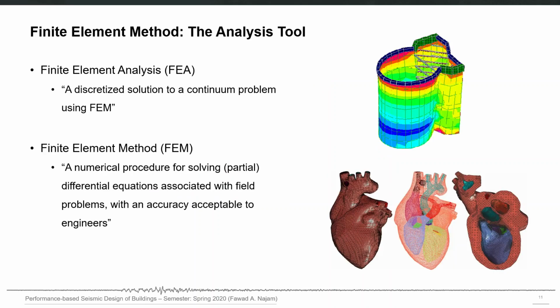The finite element method is a method based on discretization, and the underlying idea is that we can divide our structure into simple elements, and the behavior of those elements can be well understood and described by simple mathematical relationships. So finite element analysis is a discretized solution to a continuum problem using FEM, the finite element method, and that method is a numerical procedure for solving partial or ordinary differential equations associated with field problems with an accuracy acceptable to engineers.